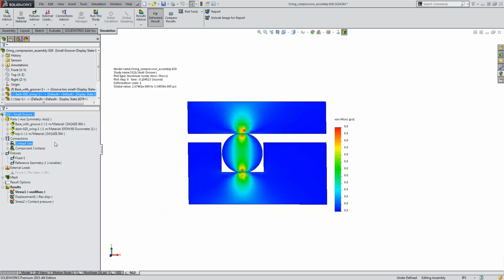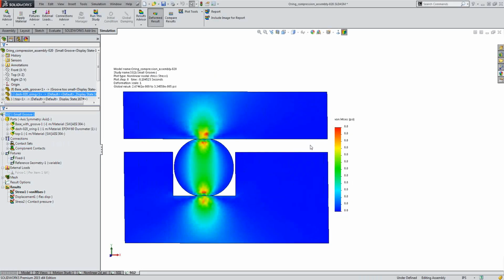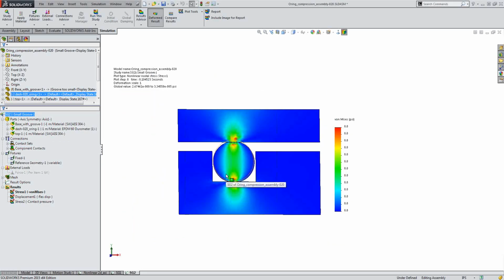At the point where the rubber starts to hit the side walls, the analysis was not able to compute anymore, and it stopped. This is a great way to evaluate if that rubber might be too hard for these types of analysis. In this case, you might want to open up that groove a little bit more and retest your parts, or even change material.